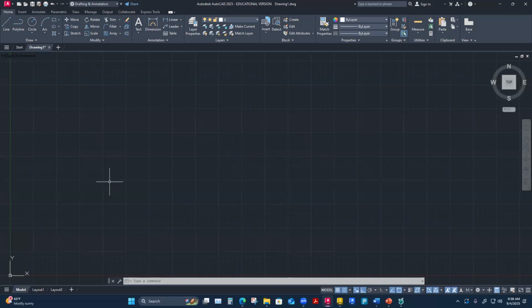And so sometimes that is one that I toggle on and off with my function key. It's F8, I think it says that when I'm over it. Ortho mode, F8 on, F8 off is a quick key command that I might toggle on and off if I want to make sure that when I'm drawing something, it stays perfectly vertical or horizontal. So that is one that I use my function key for.